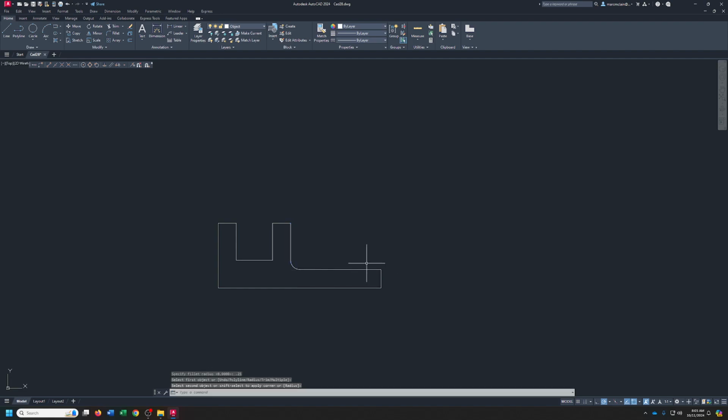And there we go. Now, we're going to draw 2 helper lines, so we're going to use the construction layer for that. I'm going to draw one line here. Like I said, I like that 1.5 spacing. If it's a metric drawing, do 40 millimeters, but if it's imperial, do 1.5. So there we go, we've got our set. So we know we're going to have one view up here and one view right here.